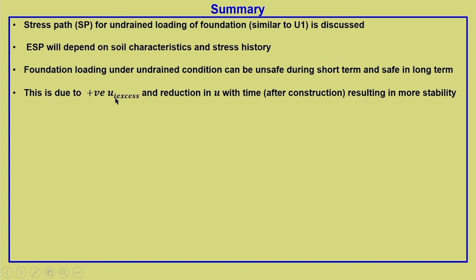This is basically due to the positive pore water pressure that gets developed and the reduction in U with time, that is, after construction, and that results in more stability. But I would like to underline here, it is progressively densifying and hence becoming more stable in terms of stress path. But what is happening to the deformation or the settlement response of the foundation? This densification is at the expense of settlement. So, we need to also look into the serviceability part of the foundation.